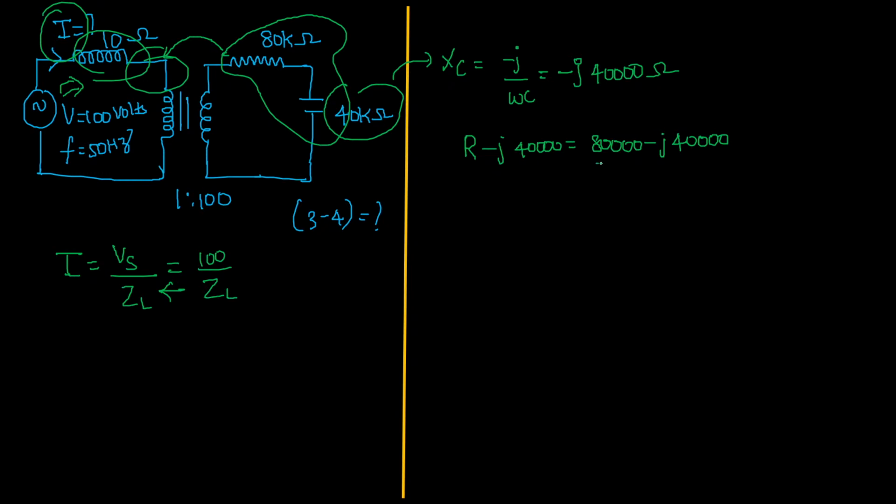First we know the secondary side impedance. How will you transform it to the primary side? This can be transformed from secondary to primary. For the primary, we take the secondary value multiplied by the number of turns in the primary divided by the number of turns in the secondary, whole power 2. That is how we are transforming it to the primary side.